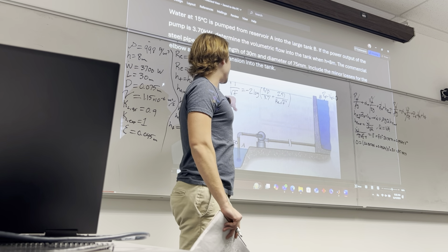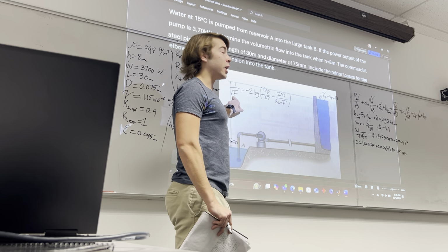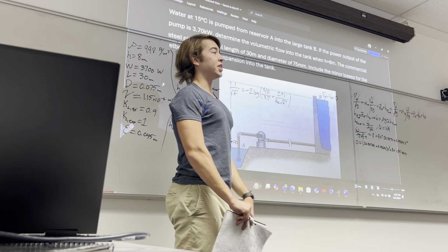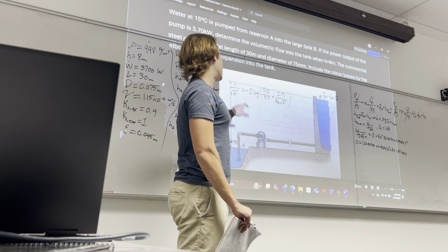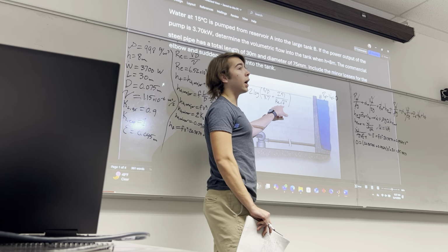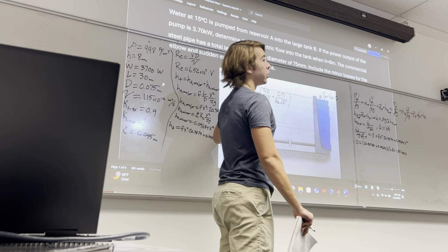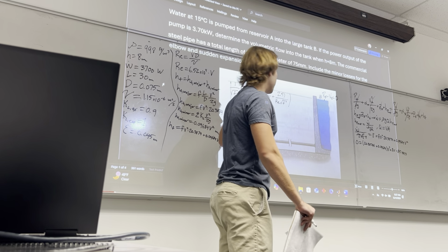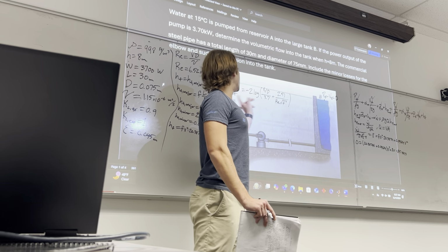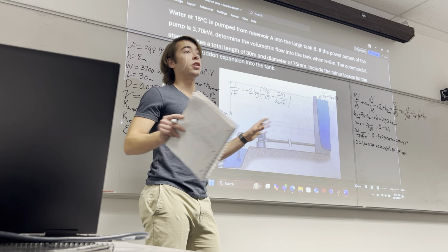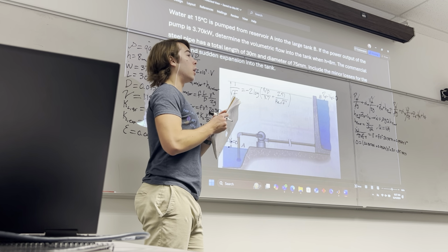Use that and then solve for this f over here, and this becomes your new f value. So you wipe everything clean, use that new f value, plug it in over there, repeat the whole thing, solve for another new f, plug it in, repeat, until those 2 f values stop changing, until they converge on a solution. All right.